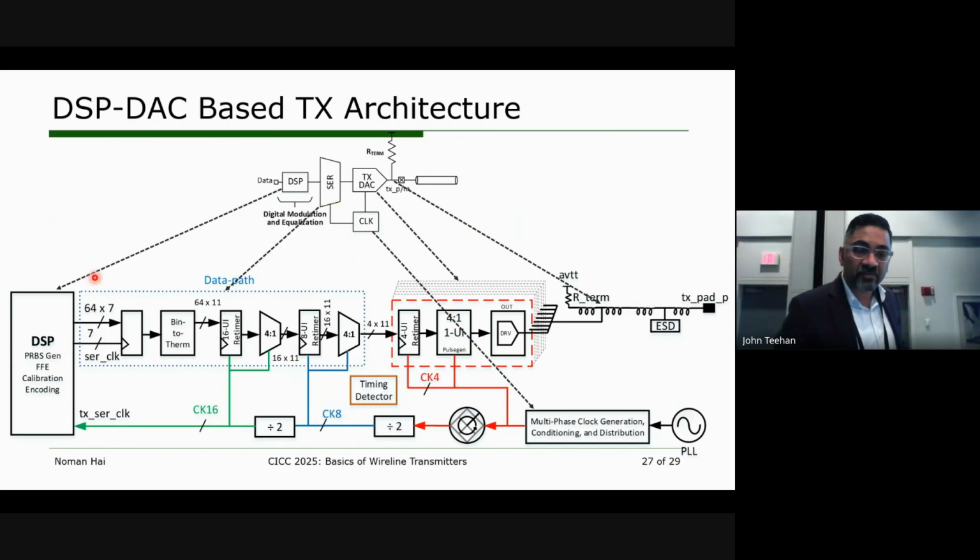So it is doing the same thing, and then muxing needs some kind of retiming of data, which comes from a digital background. So you retime the data, you mux it, and you do some processing on what kind of bits or DAC bits you need. This is done in the data path, and that final information goes to our 4-to-1 mux, which we also talked about. And that 4-to-1 mux goes to the driver through the different DACs, as I showed in this fashion, through the output to the pads.